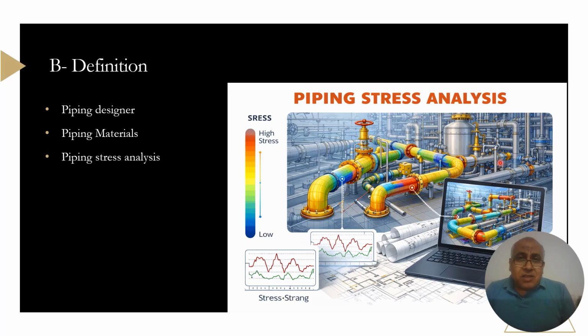Piping material is mostly about the selection of the material for the piping, the materials for the valves and so on, because sometimes the crude oil has, for example, a higher H2S content, or in the case of petrochemical or refinery, maybe we have different materials. We need to select the steel material to avoid corrosion and ensure durability along its lifetime of usage, and to adjust for the regularity of the hydrocarbon inside the pipeline and so on.